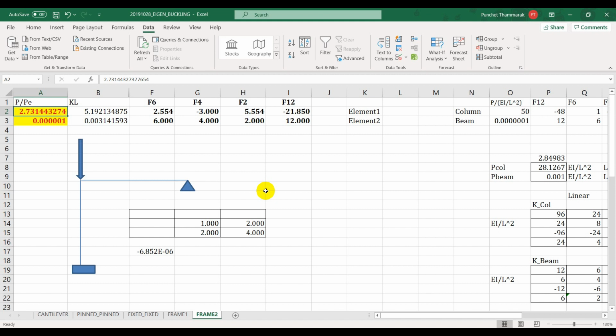But if the system is not failed by the sway mode, it is by the buckling at the middle of the column, then if you don't make the node at the middle, you don't pick up the phenomena that involved with the buckling, you overestimate the buckling load. So that's the way it works.